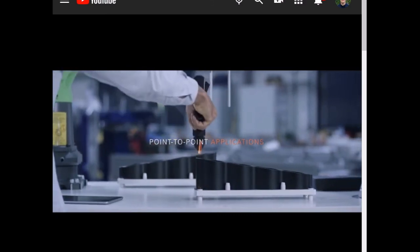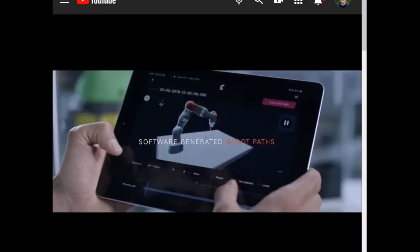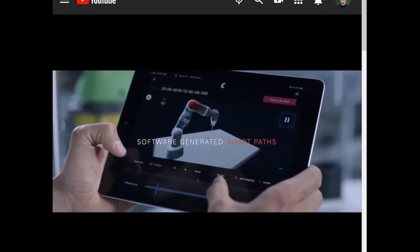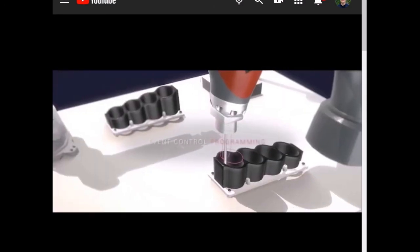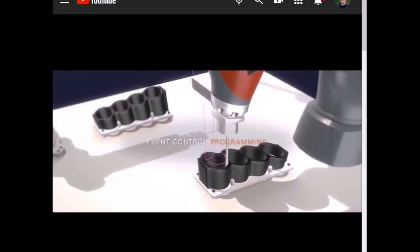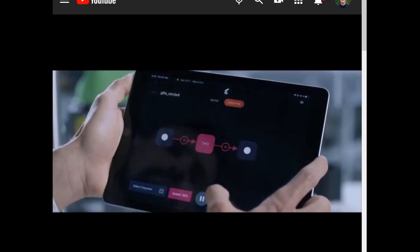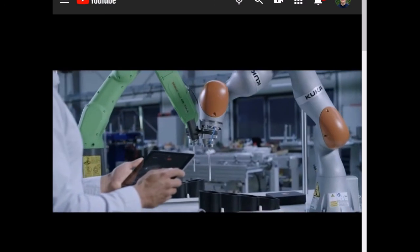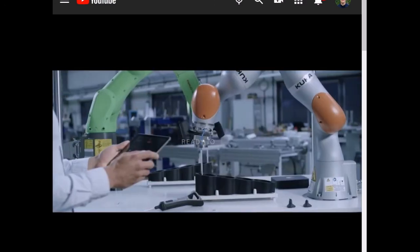One consideration when it comes to this video. I'm not 100% certain how this application works, but based on my understanding, I assume that while this seems to be a rather straightforward way to program industrial manipulators, you are actually then once again dependent on the accuracy of the industrial manipulator rather than its repeatability, which means that you probably will have to employ a calibrated industrial manipulator.